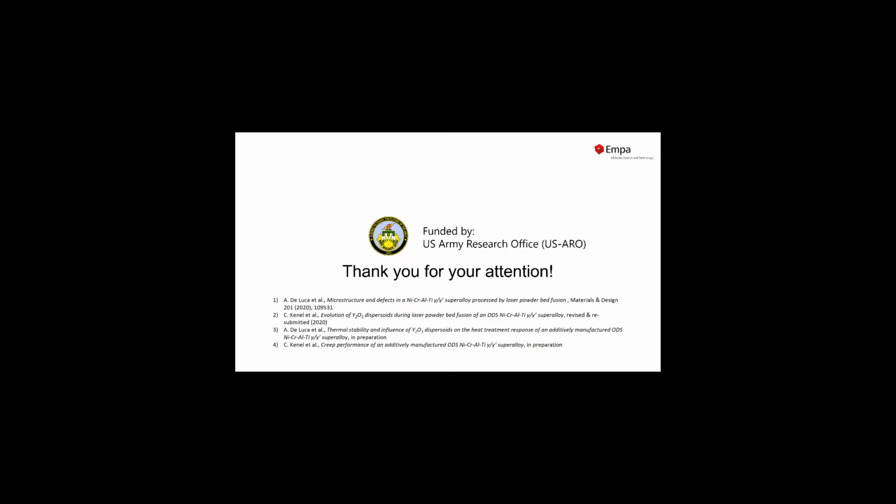How would you explain the presence of both aluminum oxides and yttrium oxides based on a thermodynamic, chemical calculation like that? Because for me, in 316L, it should only be manganese oxides or silicon oxides because they're very close to each other. But for aluminum and yttrium, I don't understand why they should both be present.